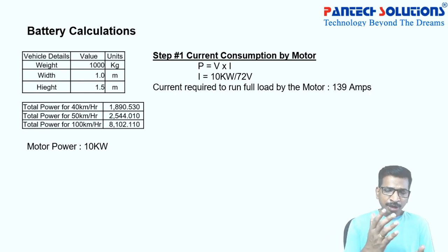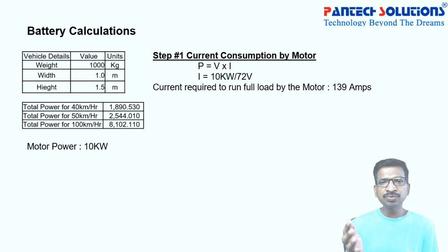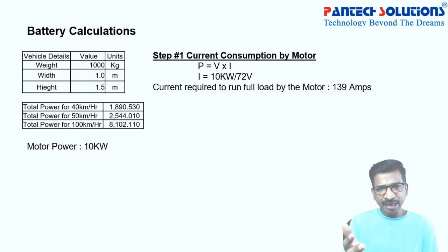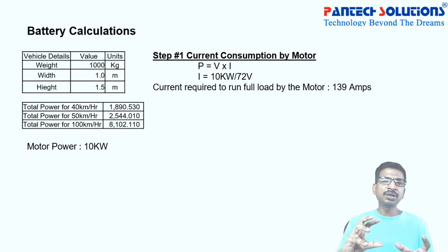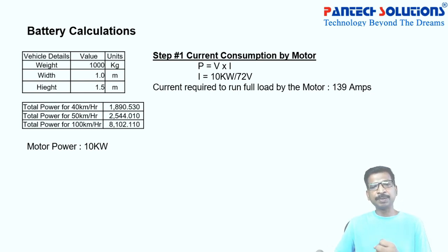And now you have an option. You can use either 48 volts or 300 volts or 200 volts, whatever you want, you can choose. If you increase the voltage, the current is going to decrease. If you decrease the voltage, then the current is going to increase. So like that you can choose. You have to fix any one of the values. First you have to choose the motor and fix the terminal voltage of the motor. So this is again your choice to fix the parameter.